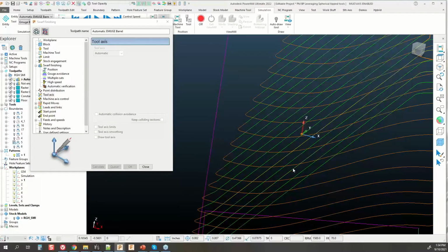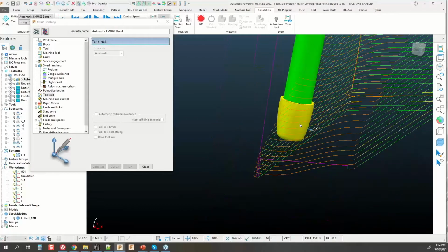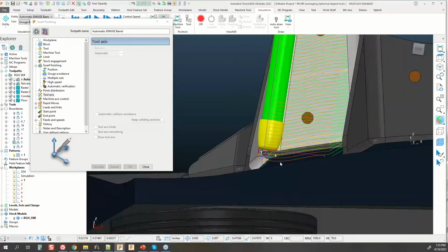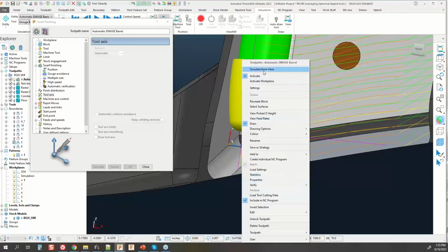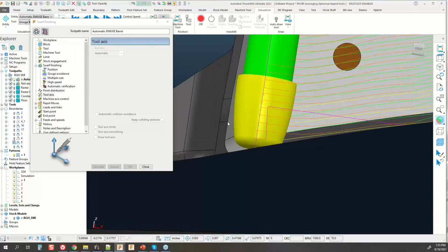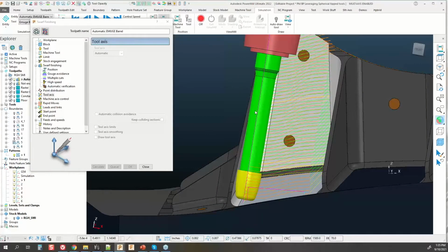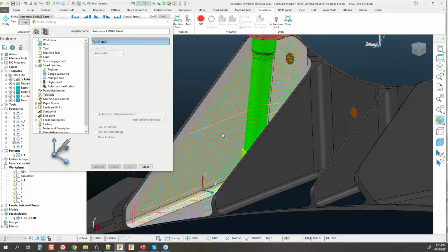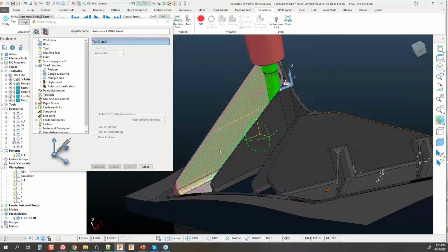So if I come down here towards the end, we're going to actually see that, and if I can get it to select the toolpath, there we go. You know, we're still quite a ways down on that. Even when we get to the bottom of the toolpath here, we're not actually going to be able to blend that radius at that contact angle because of the backside of our tool. Now, again, choosing your selection of your tool is going to depend on rigidity, reach, things like that. This actually did a pretty decent job of getting down below there as it travels up. I have just enough angle and just enough clearance to get away with this.